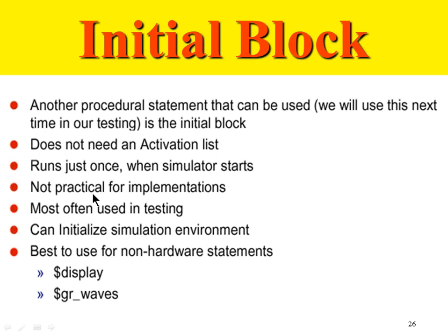Initially, when Verilog came out, it was not synthesizable, so it was not meant for implementation. But nowadays, the initial block can be synthesized and logic can be implemented on an FPGA or hardware ASIC. It was used mostly for testing earlier. Nowadays, it can be used for testing and design purposes.